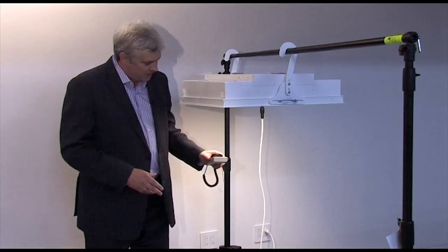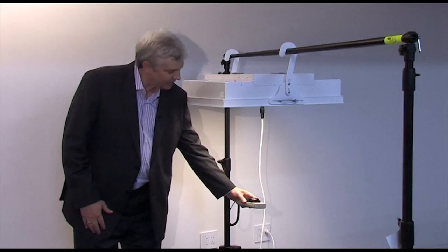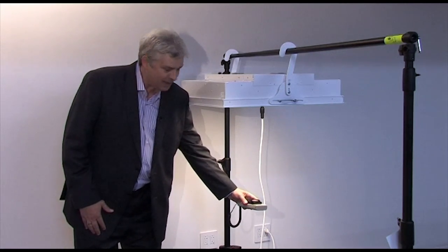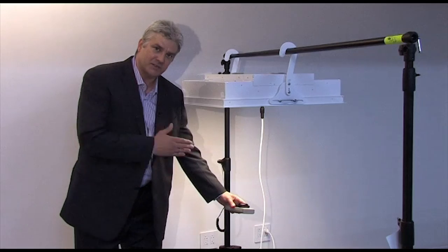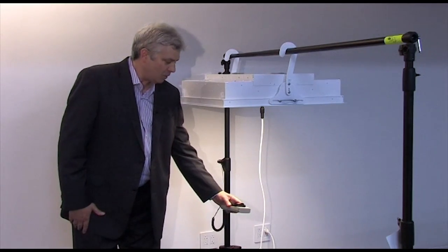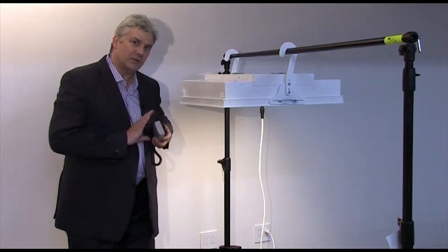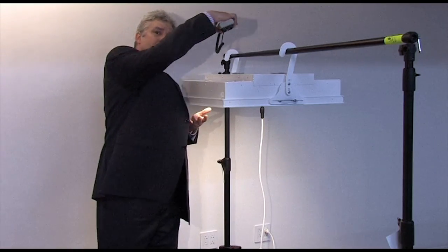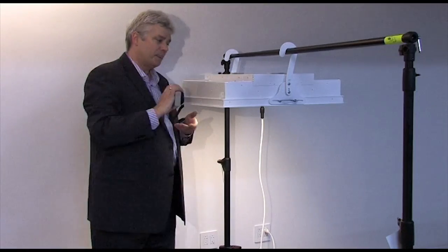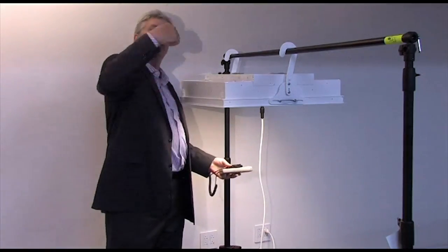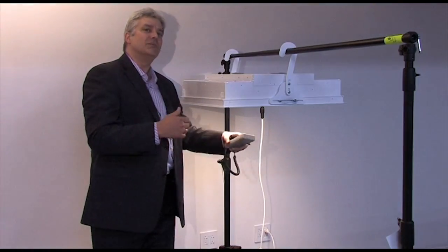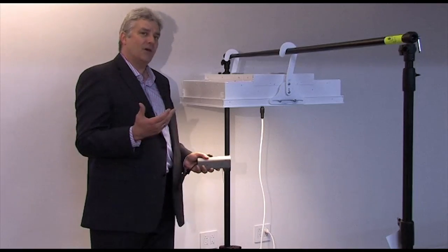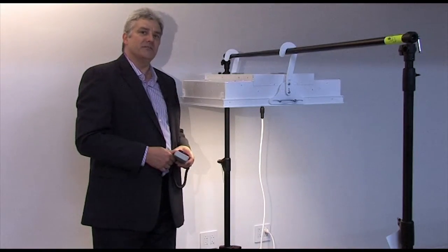What we do is we put a measuring device, measuring candelas or candle power, which is light intensity, at 0 degrees. We measure the candelas at that point. We then move it 5 degrees and we measure the candelas at that point. We do 5 degrees all the way around the luminaire, even above it. Once we've gone the whole 360 degrees, 0 degrees being beneath the fixture, we turn the fixture 45 degrees and we do the whole thing again. Depending on the fixture, we may do this at various different angles.